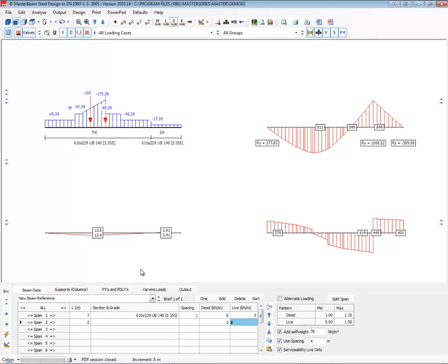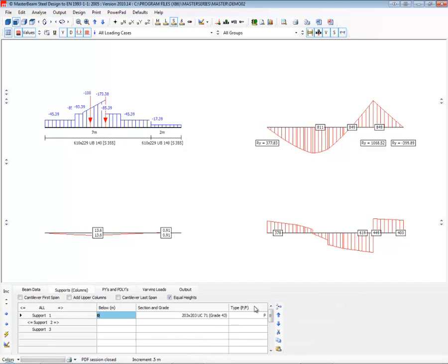So I've got my little beam here. I can come along and I can say cantilever the last span, so it's now working as a cantilever, which hogs that back down or sags that down and puts a very small hogging moment there. So the cantilevers are not a problem. So we can do a little back span arrangements using this. I can have up to 16 spans.